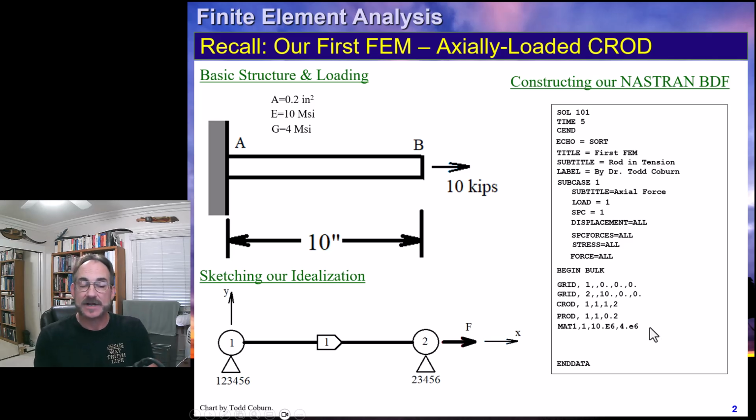Now remember, with NASTRAN, since Poisson's ratio, the elastic modulus and the shear modulus are all related, usually NASTRAN frowns on you reporting all three, because they usually won't completely fulfill the relationship between the three that's common in most materials we're using in practical engineering applications. So usually you input two of those and let NASTRAN calculate the third.